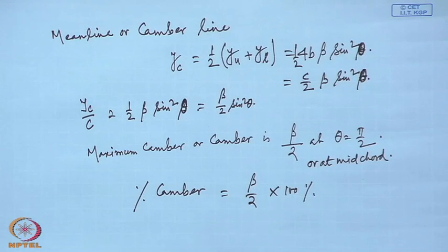These are of course not very good characteristics for a real airfoil. Usually a cusp trailing edge is not desired, even it is very difficult to manufacture compared to a finite angle airfoil, extremely difficult to manufacture. And also as far as the overall flow characteristics are concerned, an airfoil which has a maximum thickness so early at quarter chord, you see it is increasing its maximum within 25%, then decreasing it over the remaining 75%.